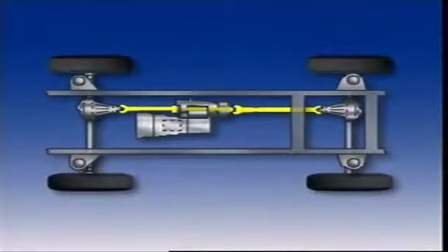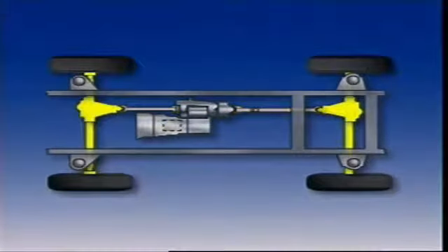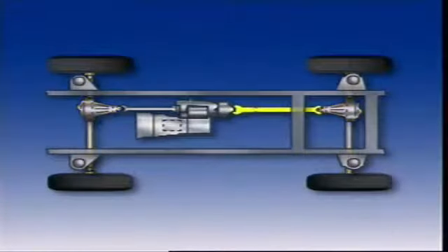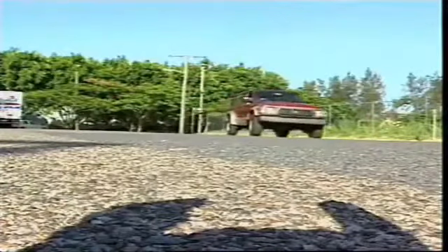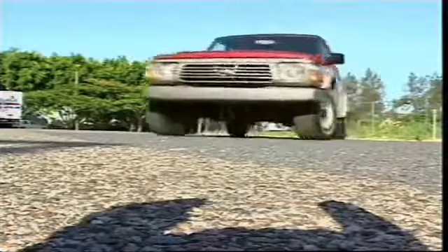It locks the propeller shafts together and directs torque through them to both axles. When disengaged, the vehicle transfer case is coupled to one propeller shaft only. When four-wheel drive is disengaged, most part-time four-wheel drive vehicles drive the rear wheels.